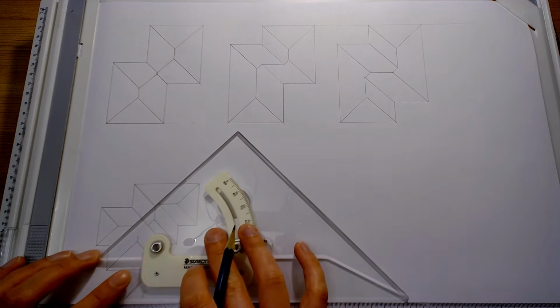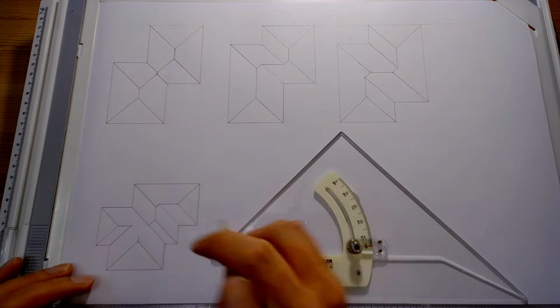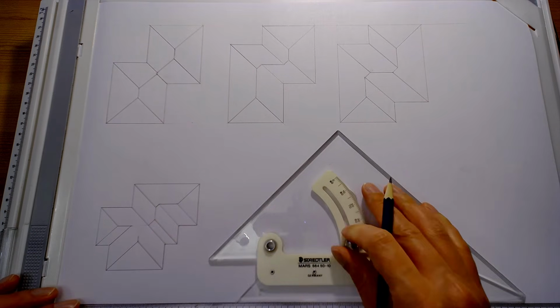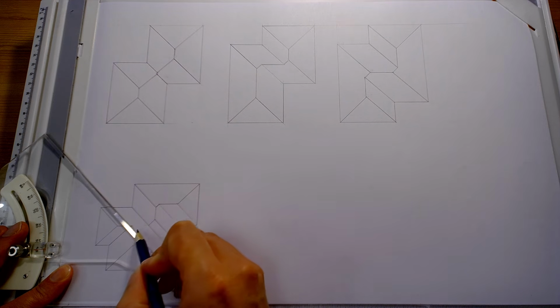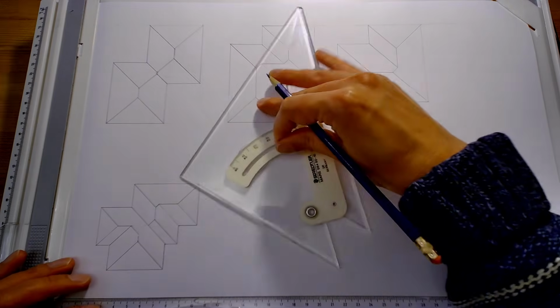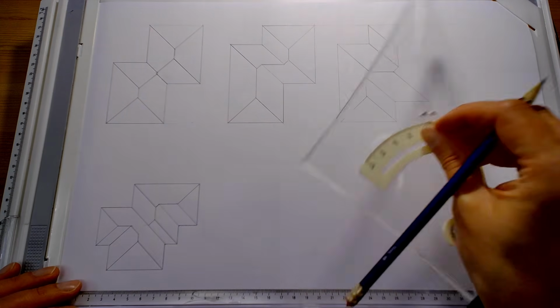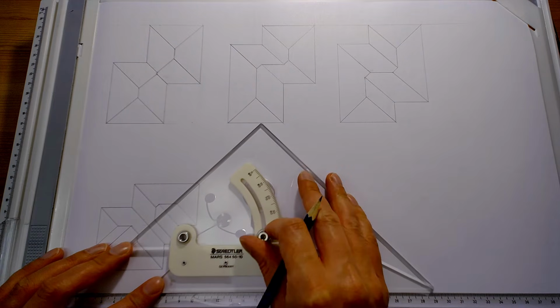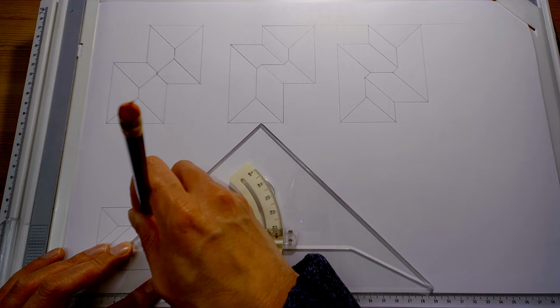But we've got this valley to take into consideration by here, so let's run that up there, and we can see that hits by there. So at that point, we need a line coming up to our ridge. And then from there, we need a 45-degree line coming down.